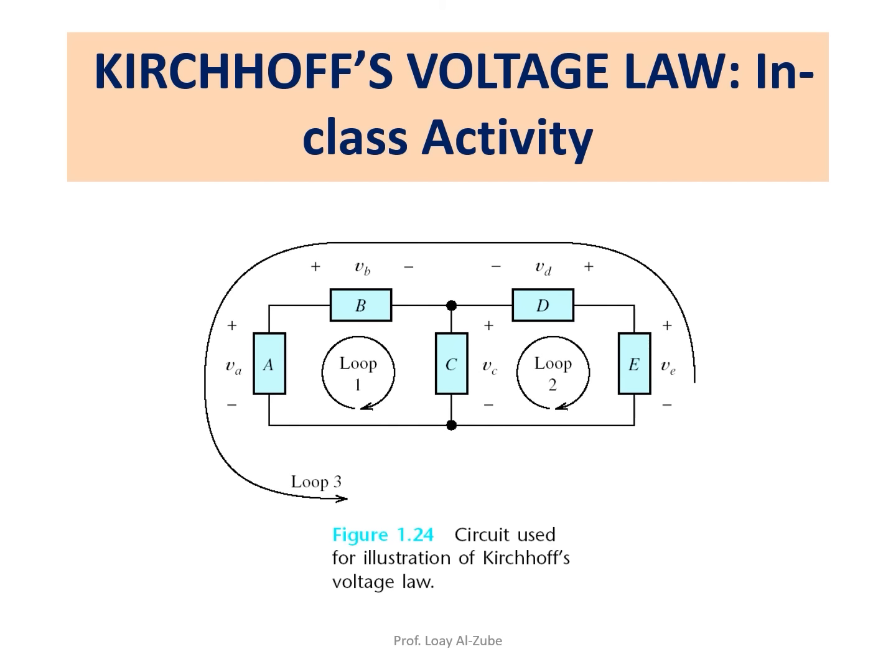So it says we need to move this way, correct? So I will say minus VA plus, see the minus is here, right? So I'm starting from the minus. And then I come here, and that's positive VB. So that's positive VB. And then I have also VC is positive, correct? Plus VC should equal 0. That's the first loop. Now, here's the thing. You need to have all loops. You have to have equations for all loops. You can't leave any loop.